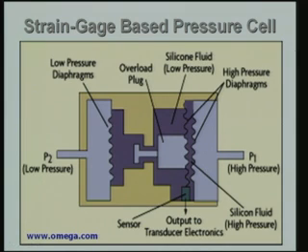So, we have discussed, in other words, two types of arrangements. One where I have a tube, a short tube, very thin wall material, and the inside I am going to apply the pressure to be measured, and the tube is going to undergo a strain because of the stress developed in the circumferential direction. In fact, we can also do in the longitudinal direction. There is no reason why you should not do. Actually, the circumferential strain is slightly more than in the longitudinal direction. That is the reason we use that. And the strain is now measured using the strain gauge.